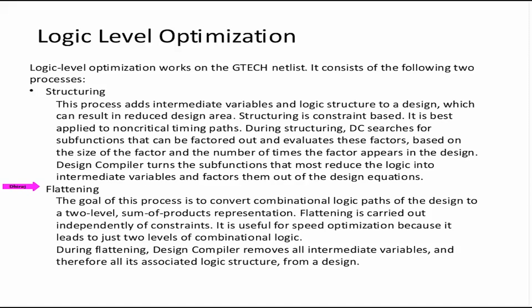Now, as opposed to flattening, DC will use structuring to reduce this sum of products into something which is more optimized based on the area.